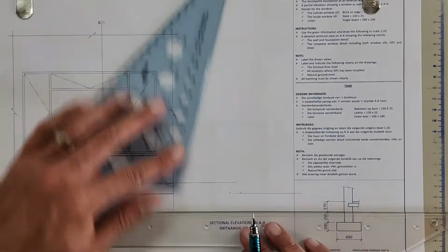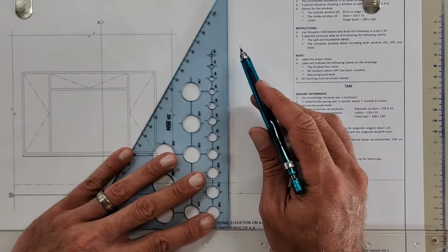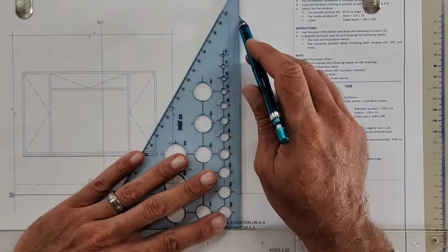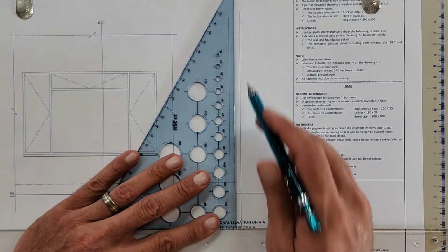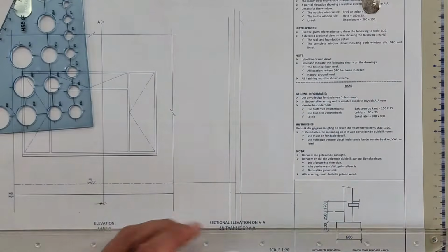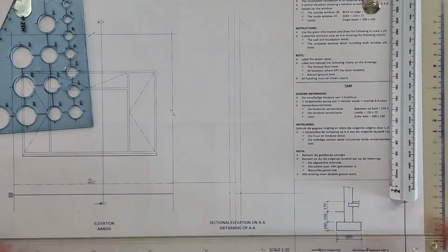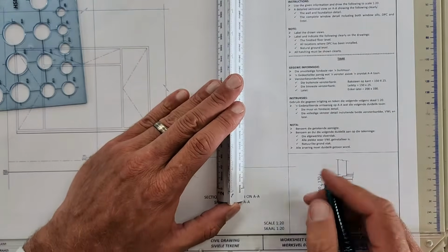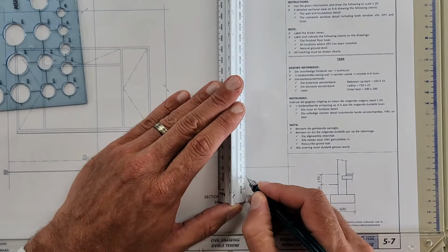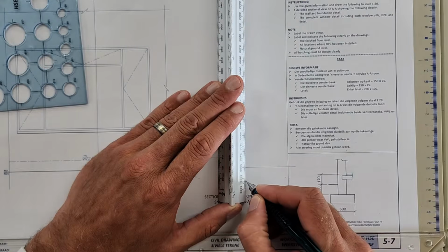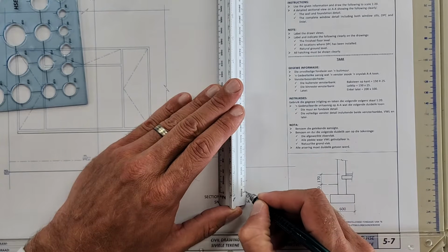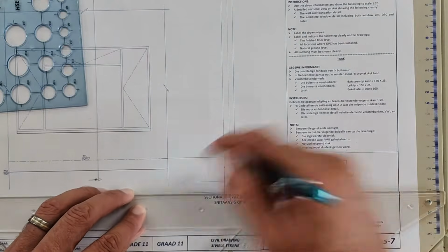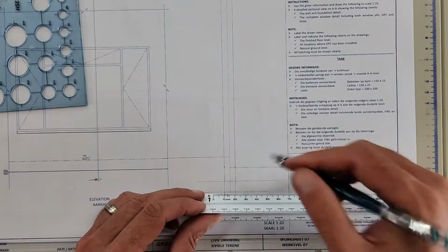You just draw a construction line going up, and another one on this side, and you can help yourself with the center also if you want to. Then from the natural ground level, it is 250 and then 200, right? So 250, that's 200, there's 250, and then another 200. And then the foundation is 600 in total.